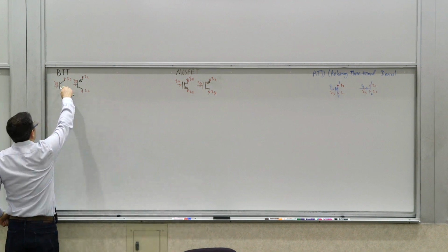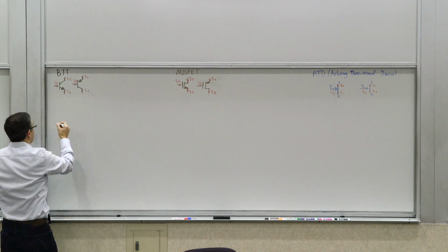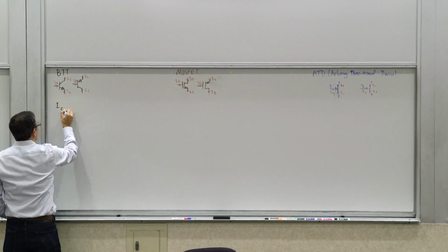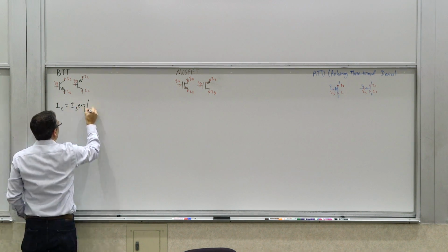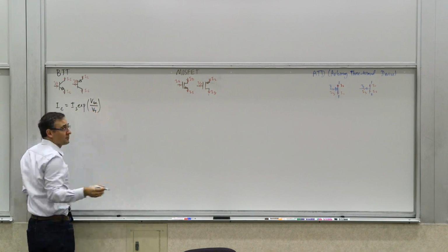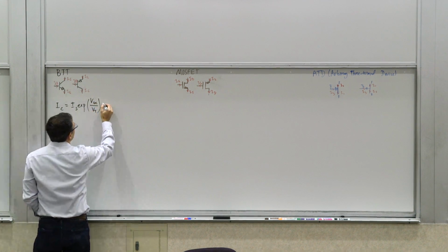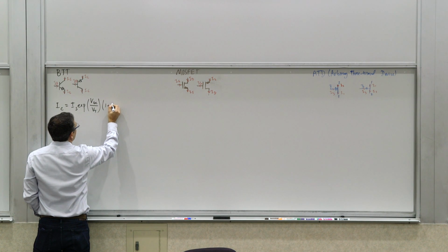And of course, the flow of the current is the opposite of the flow of the electrons, because electrons are negatively charged. But anyway, what we know is that IC to first order is really IS e to the VBE over VT. There is the early effect on top of that, which we may or may not want to write. I'm just going to put it here for completeness.